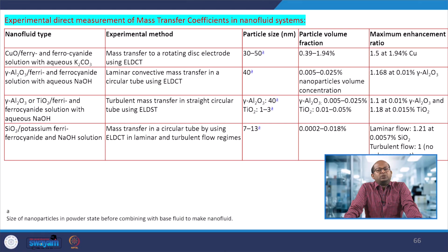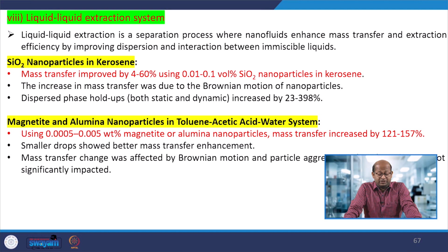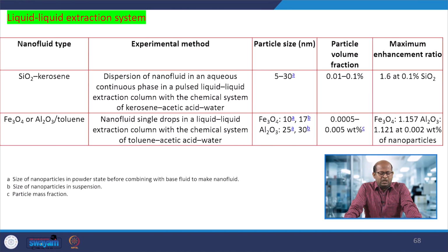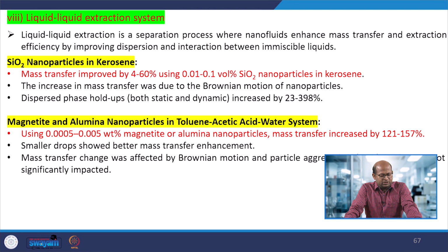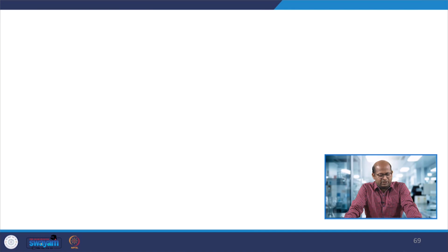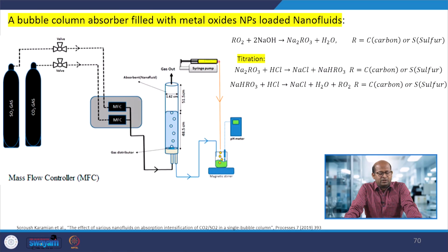So we have to use a specific nanomaterial to prepare, say, nanofluids, and then we have to use them either in flow conditions or stagnant conditions, and then the gas, a CO2-rich gas, would be passed through that. Then the mass transfer operation will take place and CO2 would get absorbed in that base fluid. So in that way we can separate out CO2.